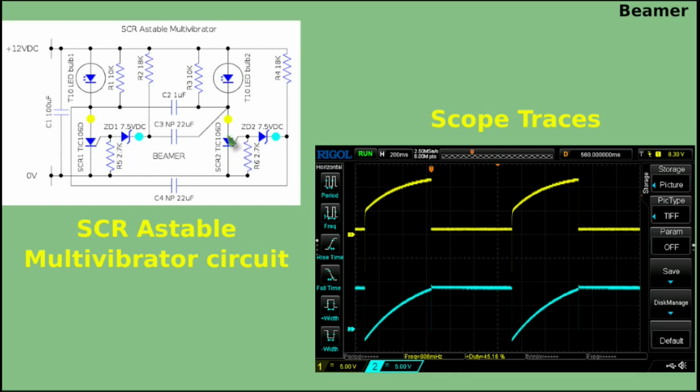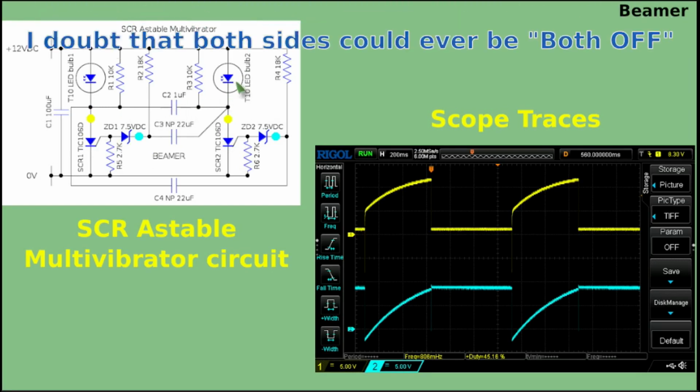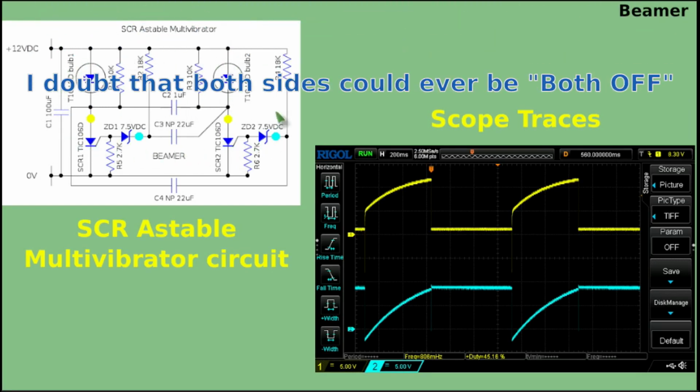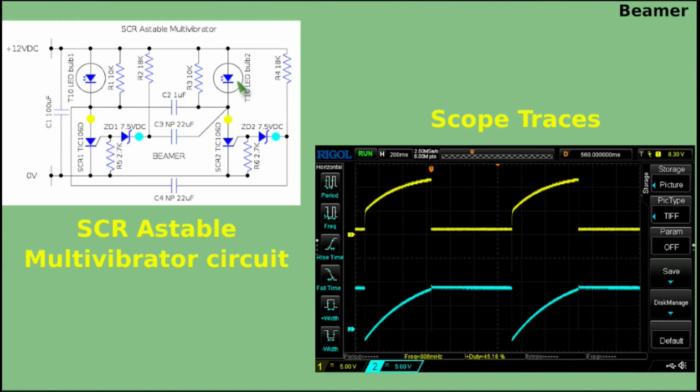They could either be both on or both off. It's because there is asymmetry going on here, that component values are different. A race condition runs on switch on, and that one will always turn on just fractionally before the other, initiating the cyclic nature of a multivibrator. All multivibrators, as far as I know, suffer from this Achilles heel, and it's very rare that when you turn a multivibrator on that both can actually turn on, but it is a possibility.